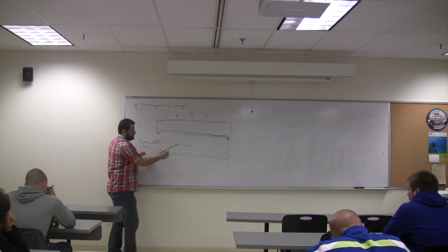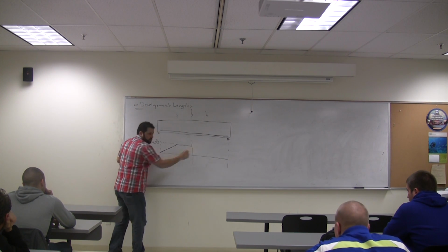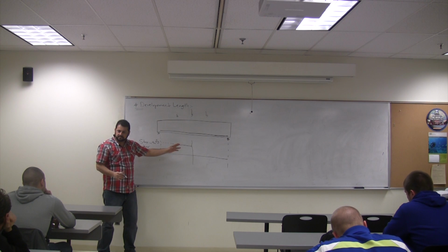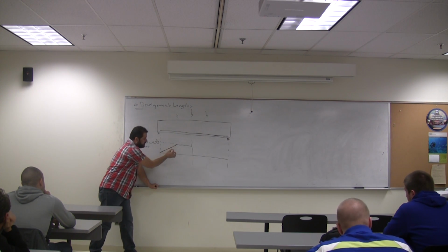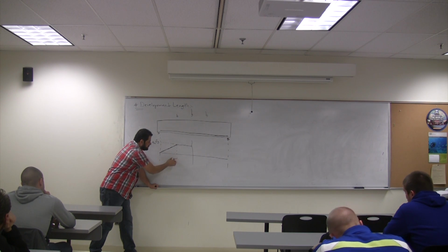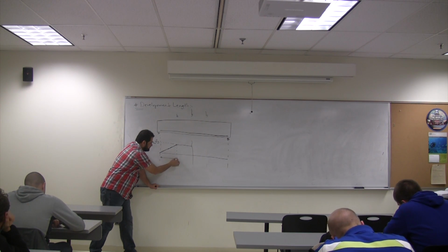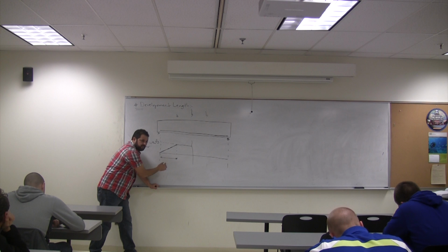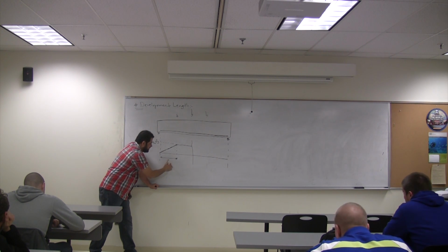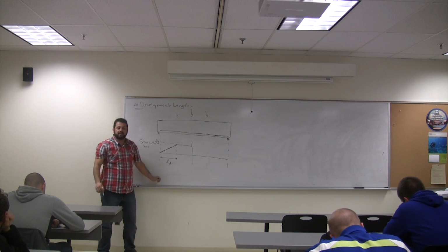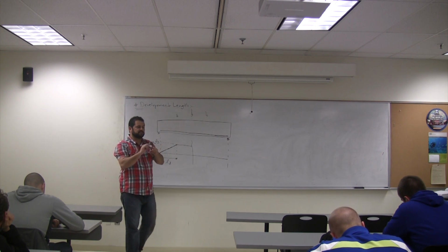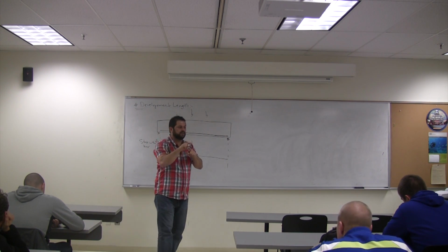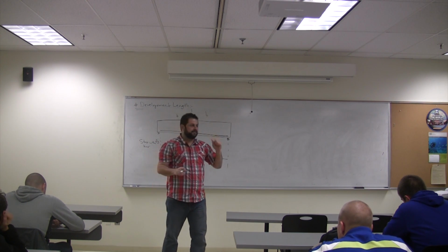Now, any idea? What should I say? So how much did it take? What's the length that it took for the bar to develop Fy? That's the development length. That's the required development length for the bar to develop its capacity. That's how much the bar must be inserted or planted within the concrete to give you Fy.